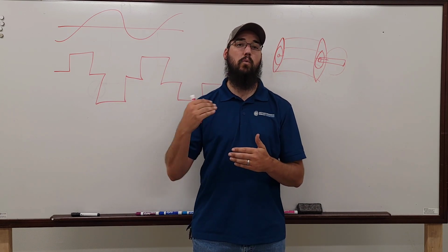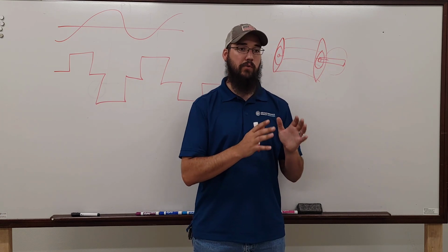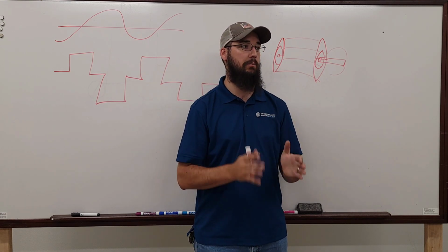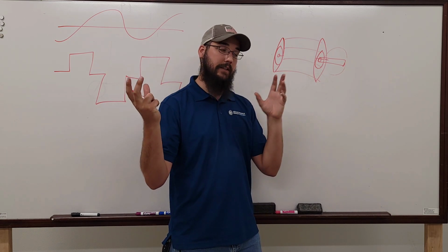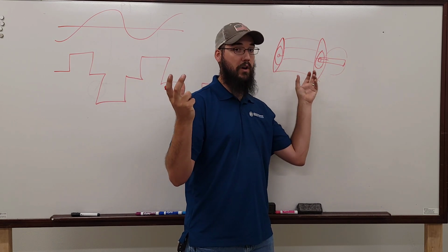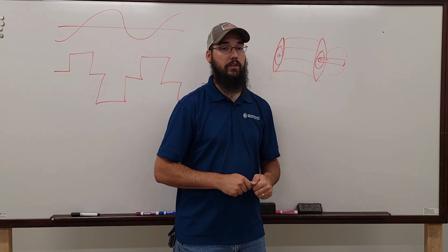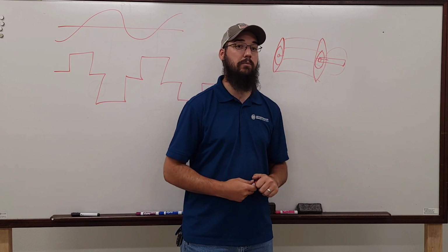That dirty power wears those out. And VFDs really perform their best when they have that clean, consistent power, when they know what to expect. You take that and add that to this as a general problem anyway, and we have motors that won't even last a year before we're having bad bearing readings through vibration.